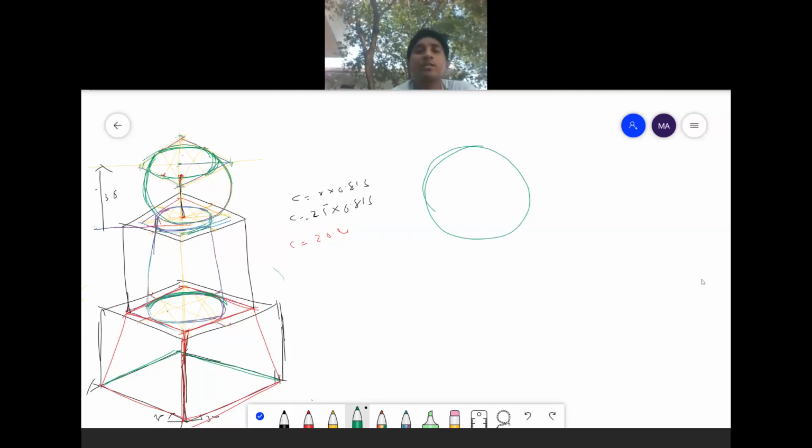First I have a circle like this, and it has a center point also marked here with a red pen. Understand? So after that, he has given clearly that from the bottom at 38 mm, this sphere has a cut section. So from the 38, I have drawn one horizontal line. From the center point, I have drawn one vertical line.